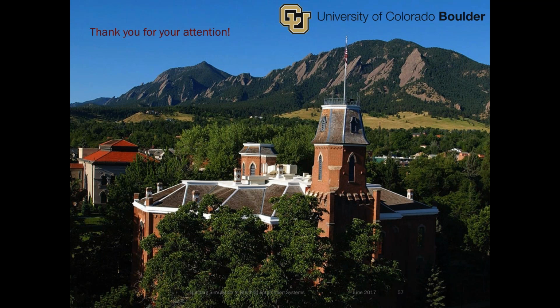Yeah. So there are two calibrations. For the offline MPC studies, whenever we utilized a reduced order model, we would use surrogate data from a complete model, for example an EnergyPlus model. We had these complex models available, and then we trained the inverse gray box models from these reference models, an EnergyPlus reference model for a retail store and for a large office building.